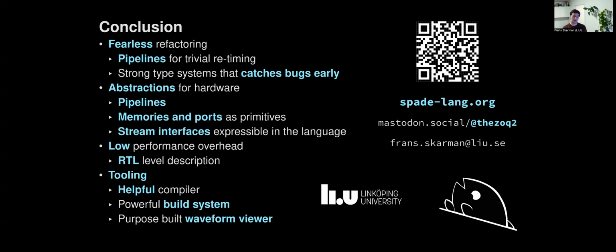Once I figured out that I need to build a waveform viewer to do this, I tried doing it with GTKWave. GTKWave supports translation, but it doesn't support hierarchical translation, which I need when I have structs. So I tried doing a string replacement on the VCD first, and played with GTKWave, and then I was like, okay, I need to write my own waveform viewer to solve this. Luckily, there are people who had done that before, so I could borrow their library.